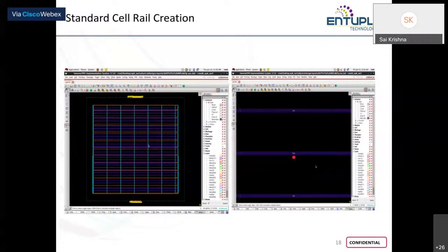Ideally, any standard cell should not cross or be placed over the left or right side boundary, because if that happens, that particular cell or the part of that cell which is out of the boundary will not be fabricated. Because of that, that particular cell or that group of cells will become dull, and hence your functionality collapses, your chip application collapses.